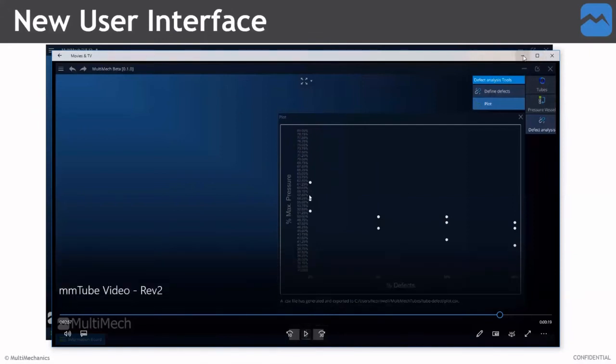So that is the tube functionality. And we also have a pressure vessel capability. For the sake of time, I won't go over that because it is the same workflow as tubes. However, we used to use a pressure vessel geometry. So it's an axisymmetric geometry that you can specify the width, thickness, and length of a pressure vessel, and it'll do the same analysis where it optimizes for the layup orientation of different plies of the pressure vessel.